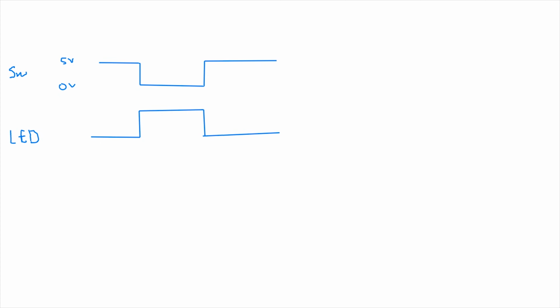So what we want to do is create something like this, where we call this LED 2, scenario 2. As soon as the switch goes down, you want your LED to come on, maybe delay for 500 milliseconds, and then go back down and stay down. So each of them is triggered by the state of the switch. Initially the switch stays at 1, 1, 1, 1, and at this point it becomes 0, 0, 0, 0 onwards.